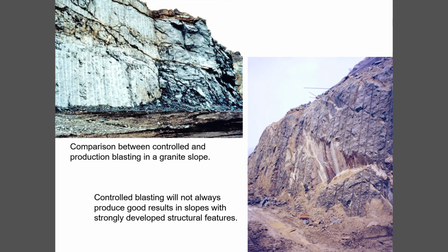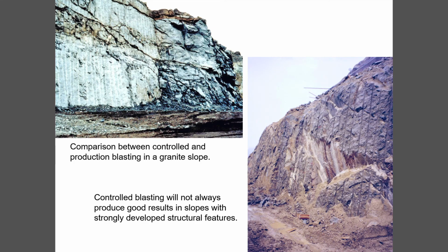Blasting is very important, and the top slide shows a comparison between what we call controlled blasting, where the drill hole alignment has been very carefully controlled, drill holes close together, and these are detonated simultaneously, so they effectively split the face off in what we call a smooth blast. And that gives you a very steep slope, which has the advantage that any rocks falling will fall straight down the slope, they won't bounce, and a much better stability than the uncontrolled blast that you see on the right of that picture. A huge difference.